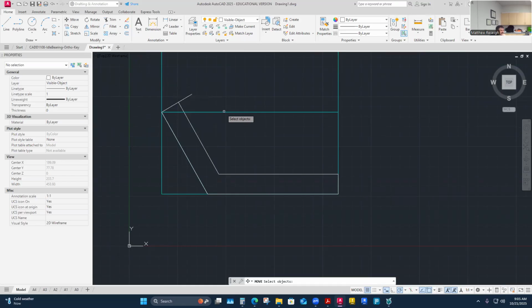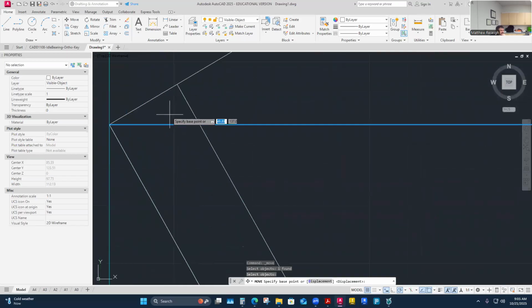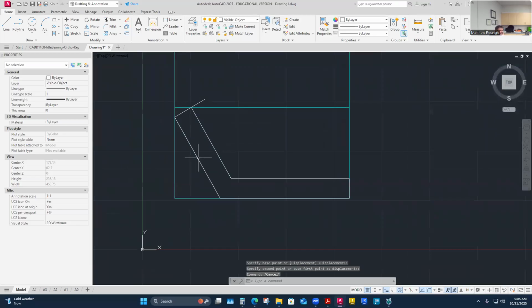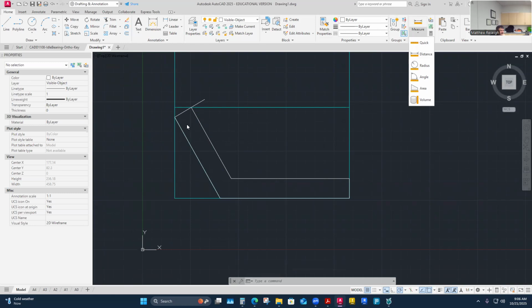I could probably move this now. Technically, this was the inaccurate boundary, but I think I'm going to snap this to there. Technically, that's the overall height here. Once I consider the thickness, how thick this is, it kind of impacted my boundary a little bit there. So just be aware of that. I initially locked it in off the 95 millimeter dimension, but that wasn't quite exactly right. So my boundary for height is 92.27.